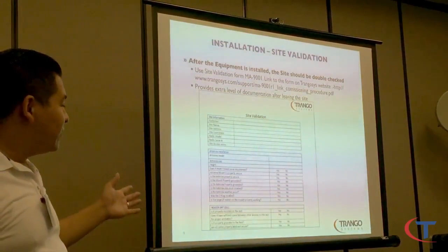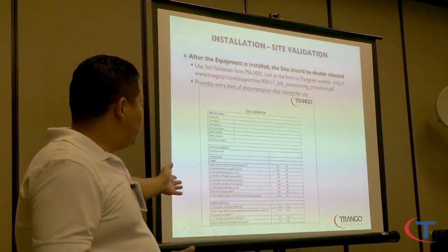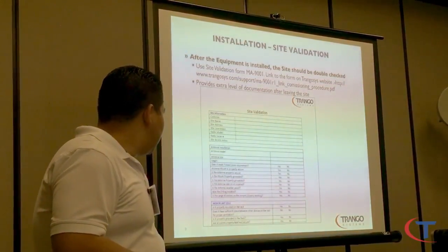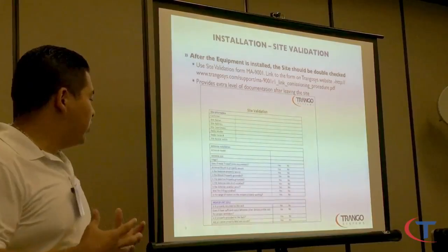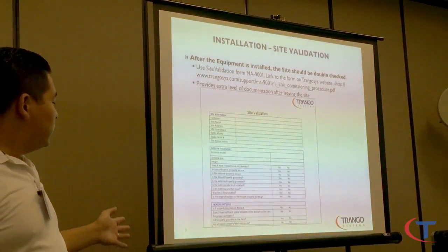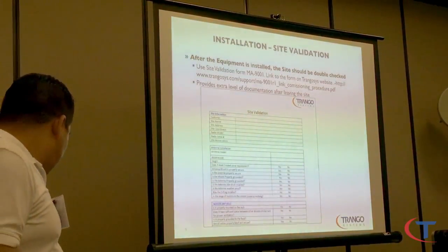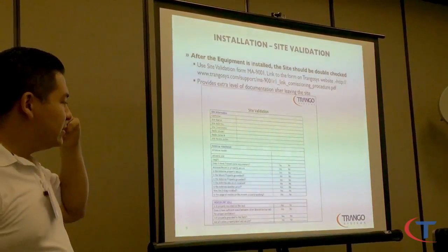Fresnel zone, is it impacted or not? Antenna mount, is it secure? Is the antenna properly grounded? The ODU is grounded. Was the O-ring installed correctly? Now, speaking about O-rings and antennas,